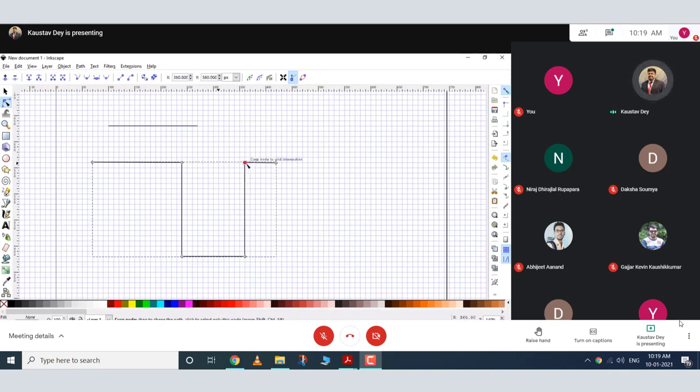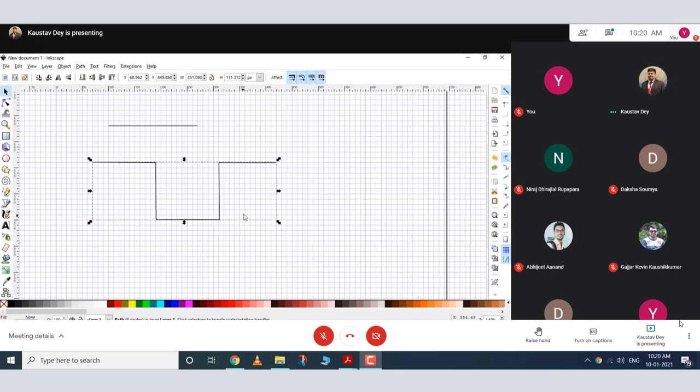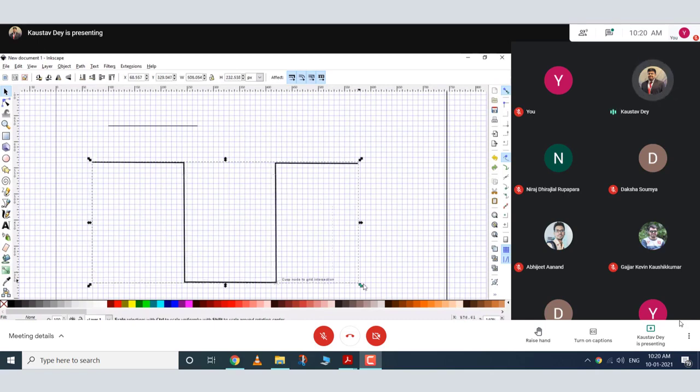I will have to stretch and drag it to the way I want the final picture to be. But the advantage is that the figure's line width does not change. It just redefines the nodes at different positions of the figure. That's all. So this is one advantage. However, in a figure like this, where I have so many different lines in different directions, this feature is quite inconvenient. I would rather stretch it here and then change the line width. However, in just a straight line, I will just choose this to extend. This is the advantage. So different things are helpful under different circumstances.